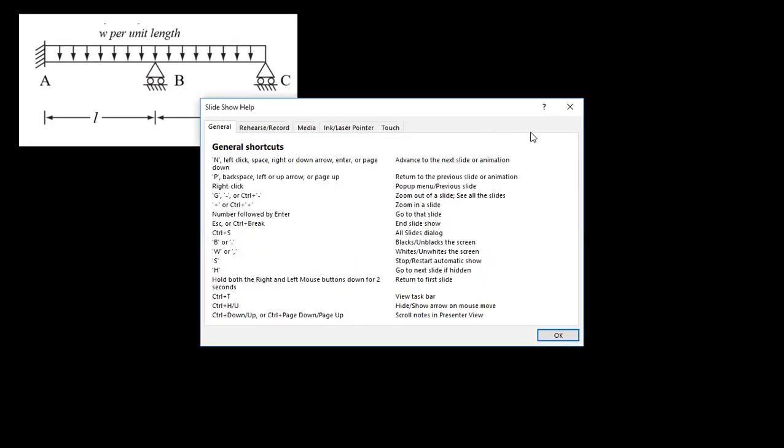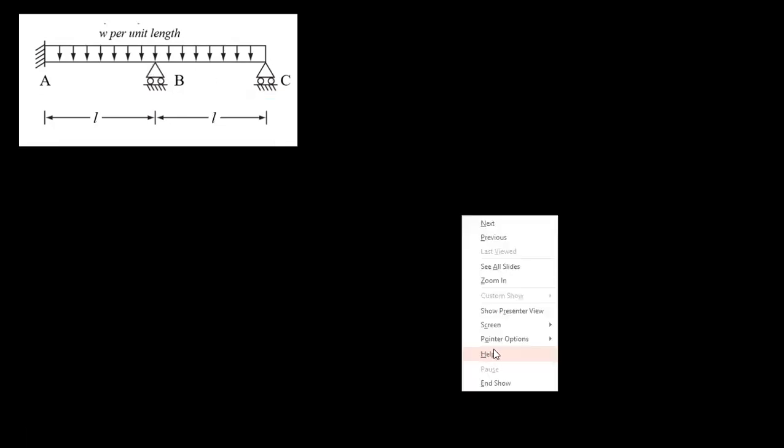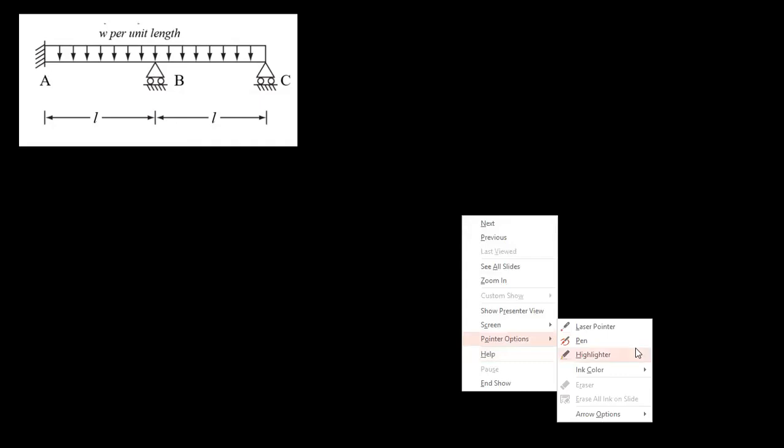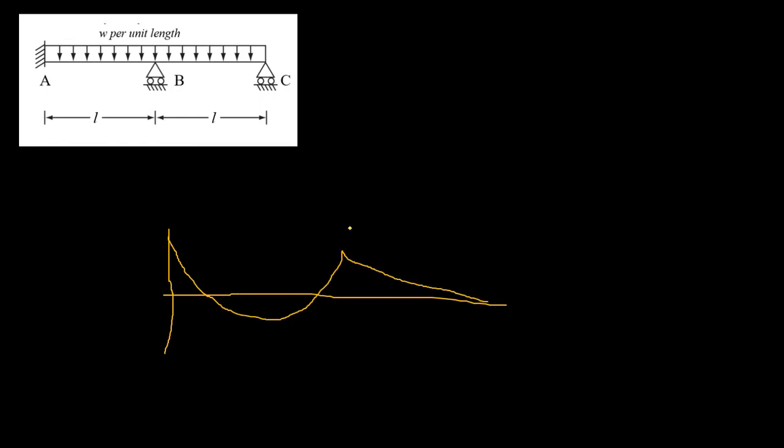There's no doubt that bending moment is 0, but you don't know this bending moment, right? So actually here also you don't know the bending moment. So if you draw the bending moment, this is not the exact shape, but probably it will look something like this, right? Here you don't know the value, here also you don't know the value. Let me call this X, you don't know the value, right? But you know the sigma M is 0, right?